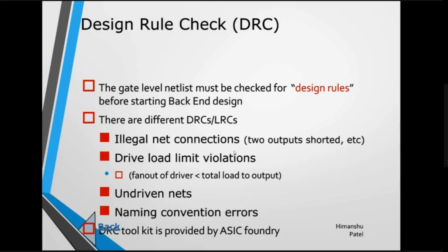For a proper SOC design, these design rule checks are mandatory, so you tell the tool to perform DRC checks. After the DRC checks, if there are no DRCs, you write a report out of these checks and verify it. Okay, everything is fine. Then you tell the tool to insert DFT.